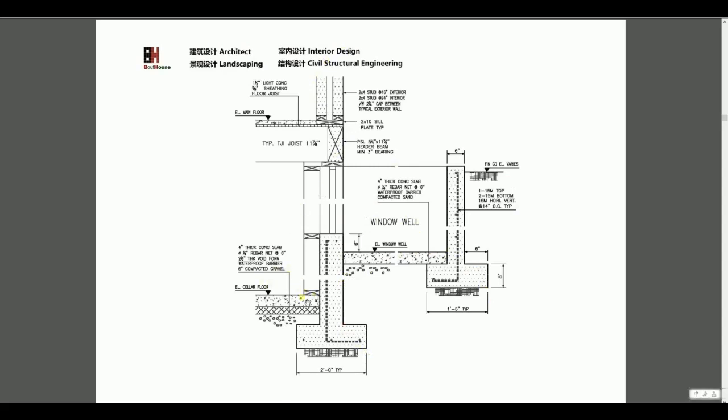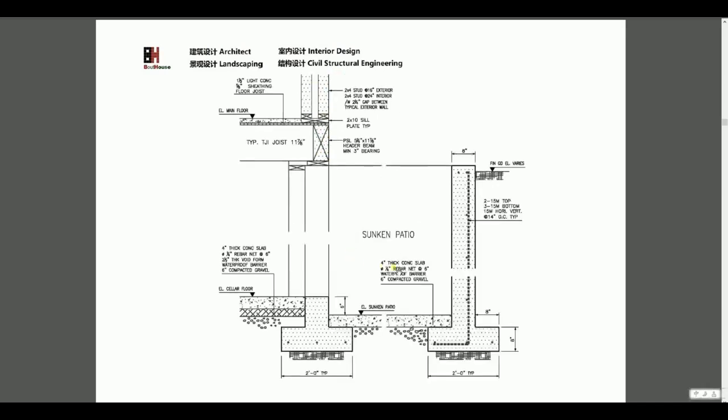This is a very common section for the window well. Sometimes in the basement we need the window well. So yeah, for the window well we have the PSL header here to support the stud wall above.